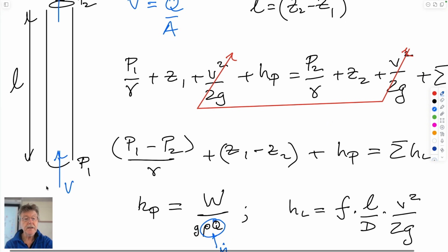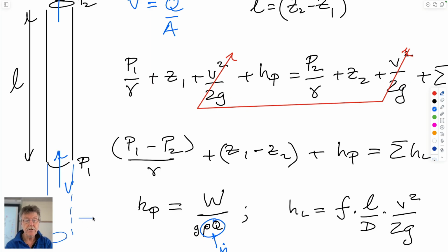So I suppose typically here, below the cap rock, you'd have a region which would be perforated, still be cased potentially rather than open hole. And so this would be the part that is gathering water and then sending it up to the top at some volumetric flow rate. So this would be Q.